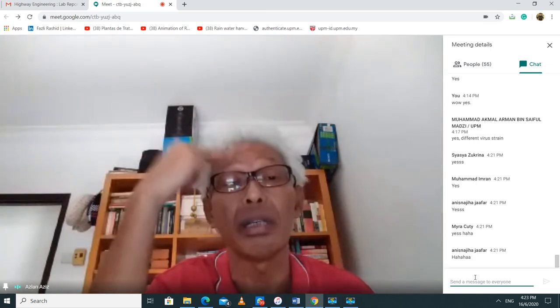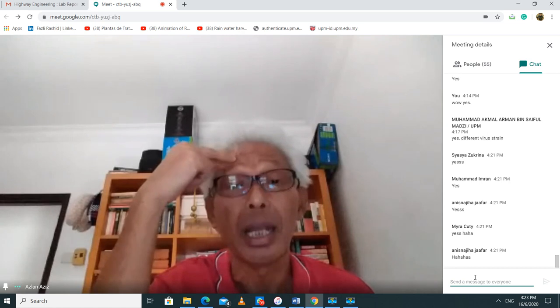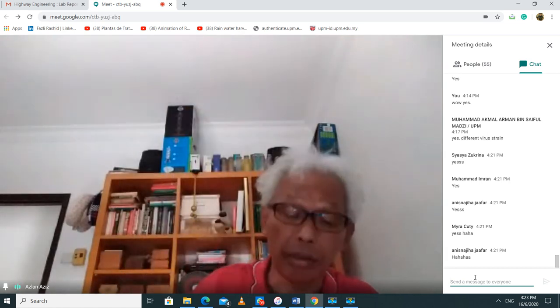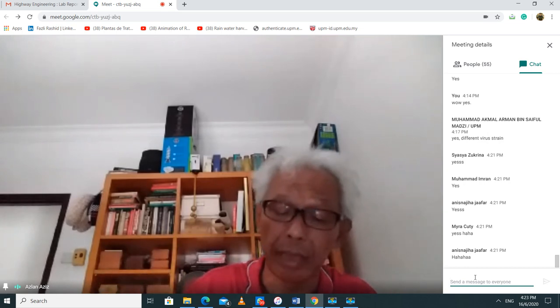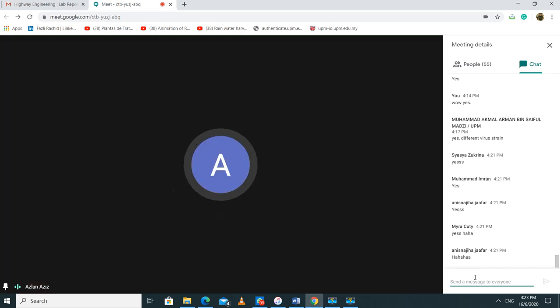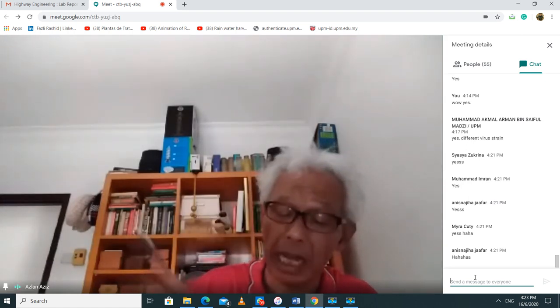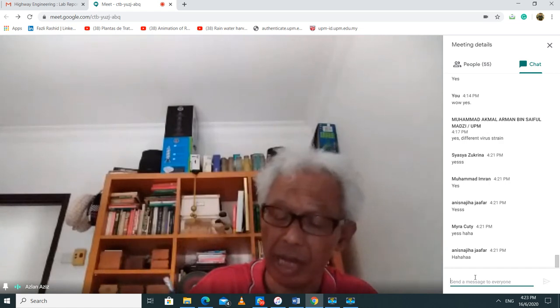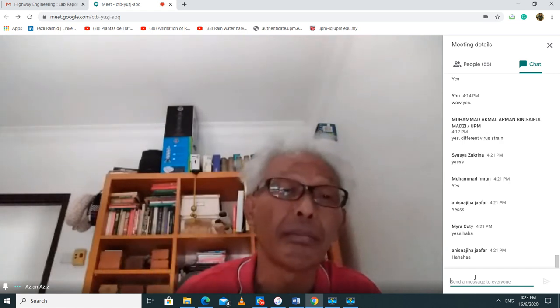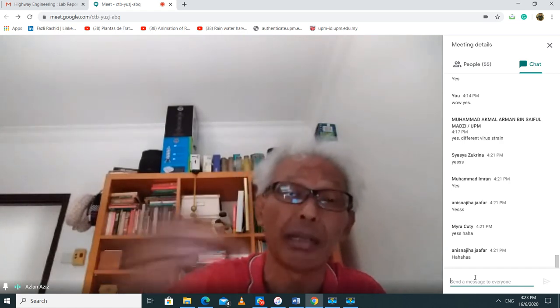So we take the sample and put it in a triaxial cell, then we apply what we want to apply in terms of the field condition under three-dimensional condition. So we find, under that load, what the settlement is, and we do this in the triaxial cell. And we repeat for all the elements. In that picture there, I have element 1, 2, 3, 4. I sample them at each of these, and then I apply all those stresses. I have the major principal vertical stress, I have the major vertical strain, and I do that a couple of times.